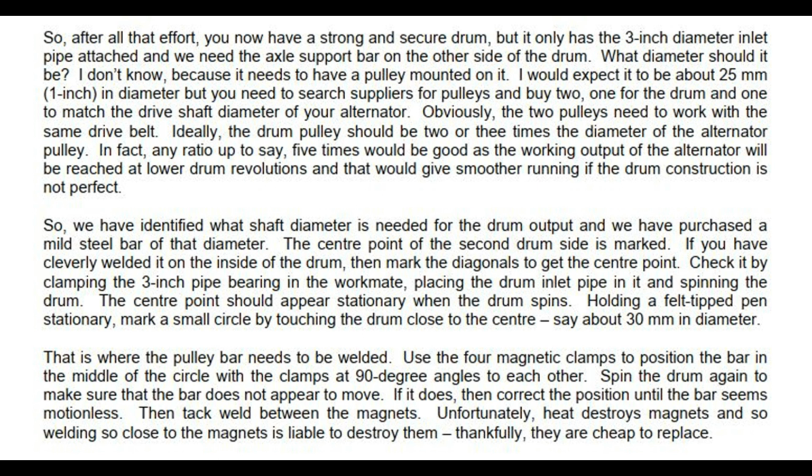Then tack weld between the magnets. Unfortunately, heat destroys magnets and so welding so close to the magnets is liable to destroy them. Thankfully, they are cheap to replace.